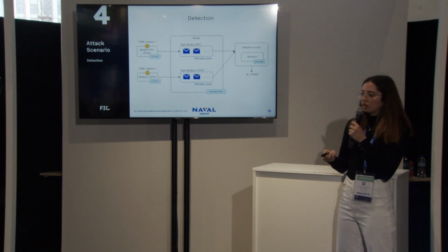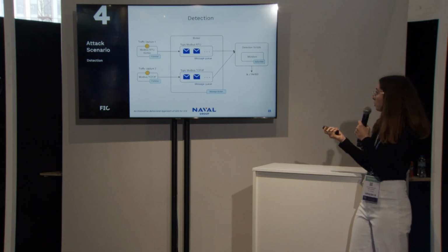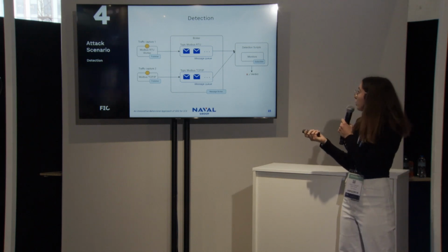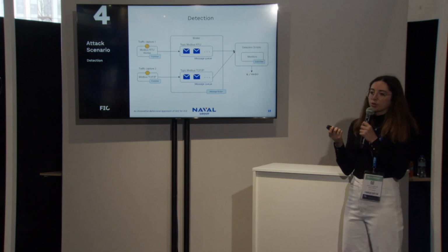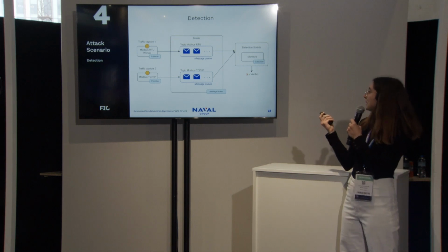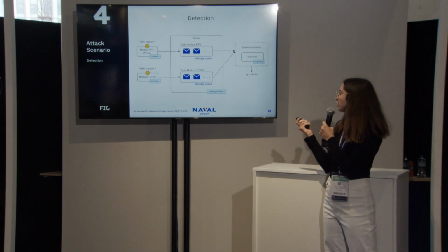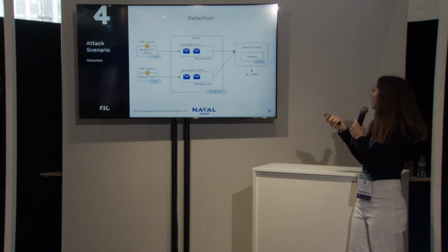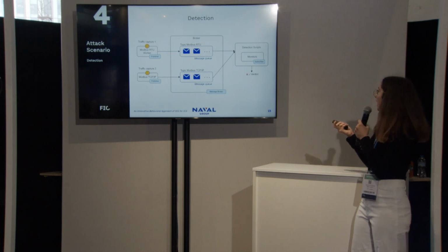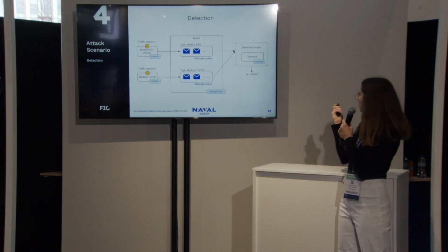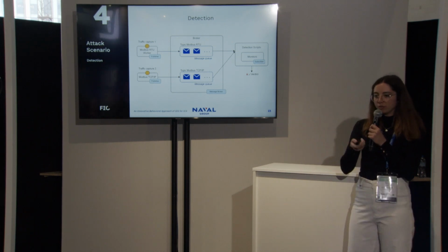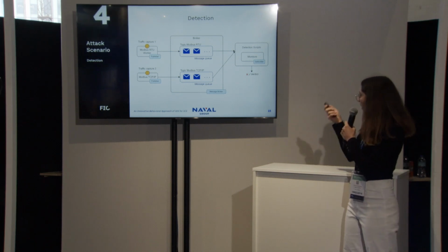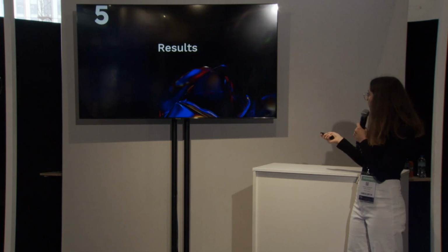Here is the simplified architecture, just to show you. We use a publisher-subscriber architecture. The traffic captures are called workers in Zeek. We have a Modbus RTU worker and a Modbus TCP/IP worker, of course. They publish on a message broker, and this allows our detection scripts and the monitors to subscribe to specific topics depending on what the monitor needs in order to give a verdict.